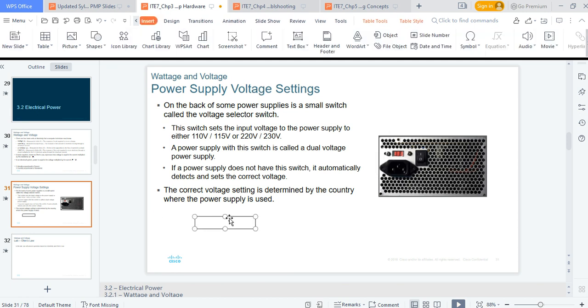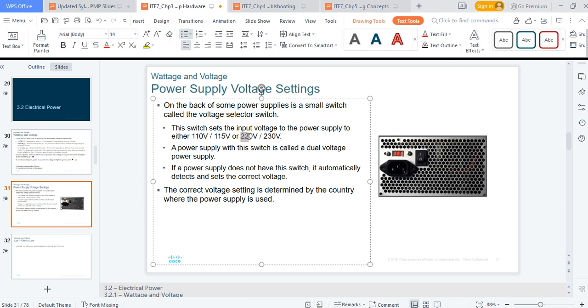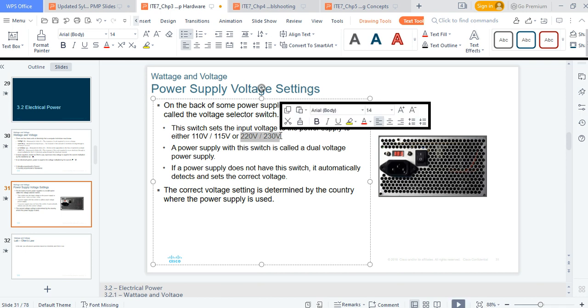After that is done, it steps down at your transformer and enters your house. At the point it's entering your house, in Africa, it's 220 volts. At times, if you have high voltage, you can have up to 240. So the point I'm trying to make is that most appliances here in Africa use this as their rating, whereas in Europe and the US you have this other rating. So if you bring an appliance from Europe and connect it to 220, it's going to blow up. That has happened to me once or twice.